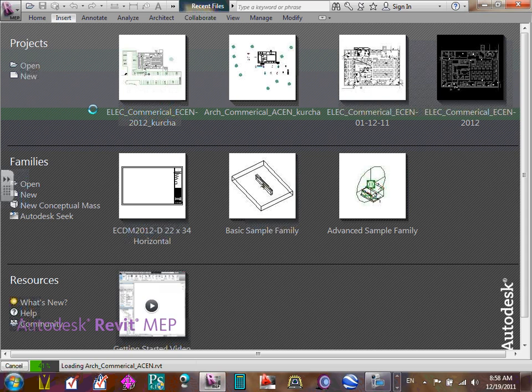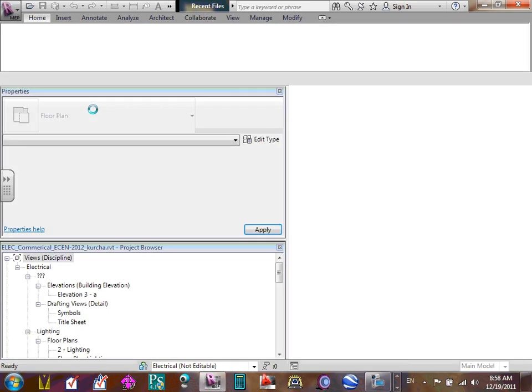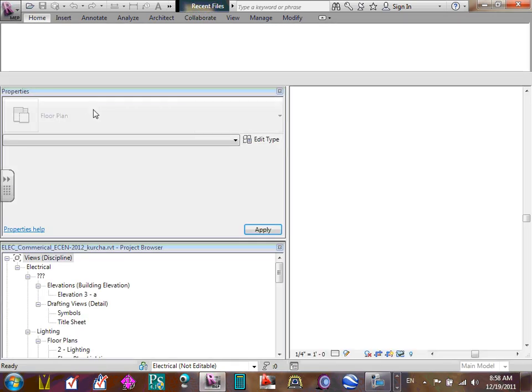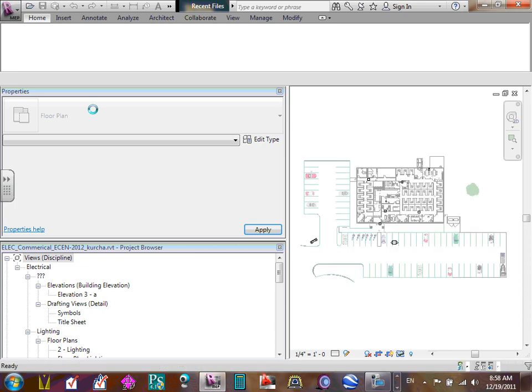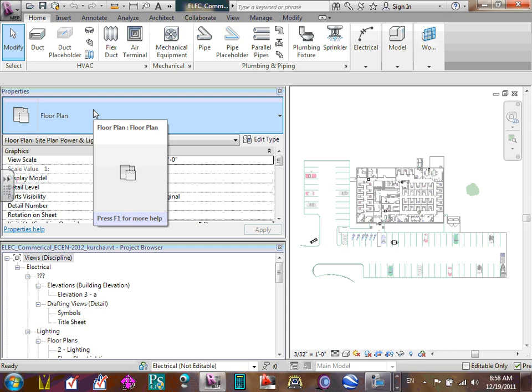I want to warn you, Chris, Nick, and everybody else, that the way we're doing the project is different than the way we did it last year. If you look at the riser, it is different than last year's. We're doing it differently. We don't have a lighting and emergency panel. We don't have a UPS panel. We decided to make the generator pick up the whole building.